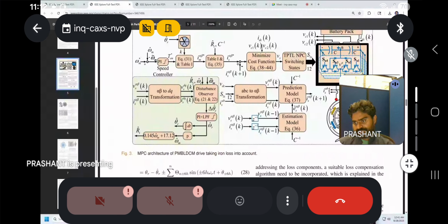Although the motor is an AC motor, we need to drive this motor using a DC to AC converter, like an inverter. Still, the name is BLDC. DC comes in the nomenclature of the BLDC motors, and another term is permanent magnet. The permanent magnet signifies that the rotor of the motor itself is the permanent magnet. So there is no separate magnet. The permanent magnet itself will be the rotor, and the DC in the name of the brushless DC motor drives, we will see there is a term DC.